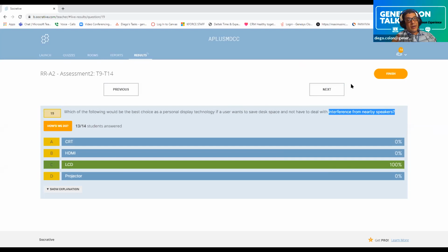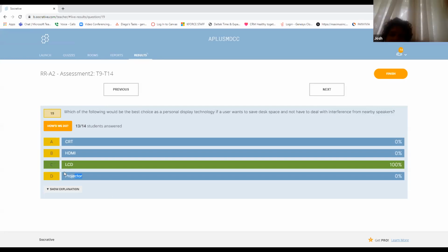That's why they also asked you that, to hint even further. I want an LCD, and on top of that, I want it to have the backlight that's an LED, not the tube. Because if it was a tube, you're going to have interference with the actual speakers if they're nearby. Again, projector would be interference with speakers. That would also mess with you, by the way.